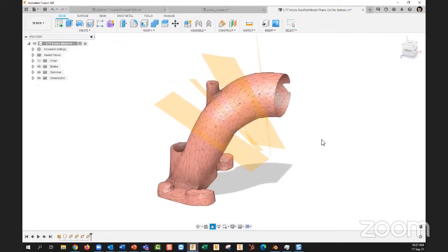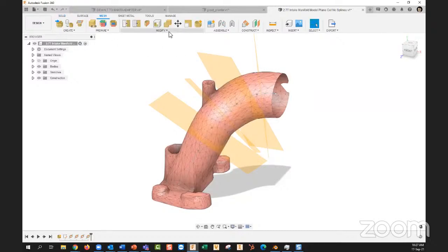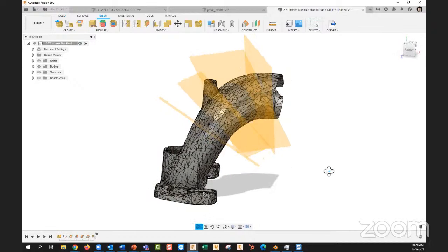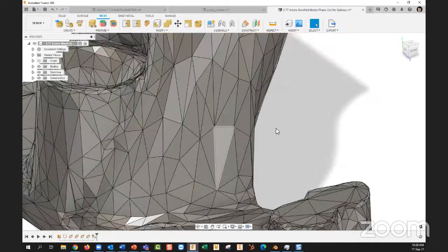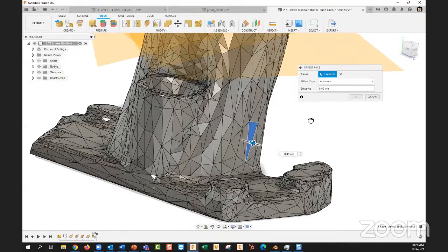And what we've done in the past, and I'm just going to show it here real quick, was we converted this into a B-rep body, and then we projected the silhouette of it. So we did the convert mesh, faceted, and then real quickly we got a bunch of different triangles that we can directly edit from the model, which is fine.